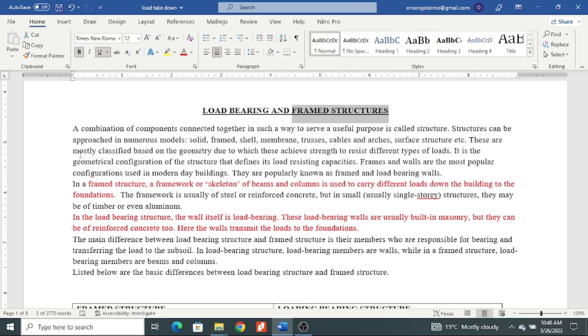It is still a framed structure, but due to bracing systems, which I will discuss later, as they are required in a high-rise structure to distribute lateral loads to the foundation, we have them in our structure. Therefore framed structures can have shear walls, and also have columns, beams and slabs as their load distribution mechanism.